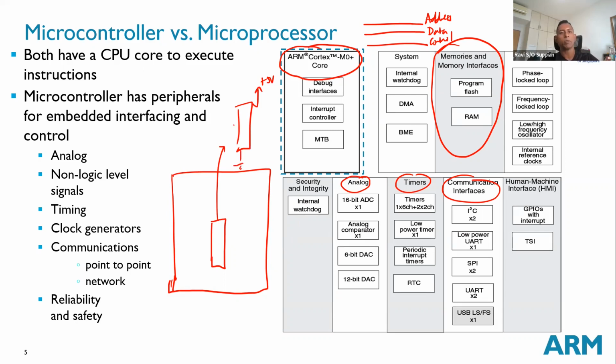If I want, I can put in an external crystal or external clock. If you remember, your board, the Arduino Uno, runs at 16 megahertz, if I'm not wrong. But even if you don't want that, you can configure it to use the internal clock. So just that chip alone with a power is actually enough to build your own custom board. The Uno board itself is very big because they just have a lot of other stuff there, but all that is not necessary if you just want to build it as a standalone system by itself.